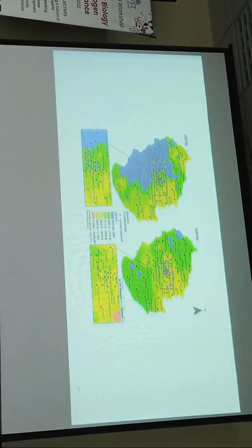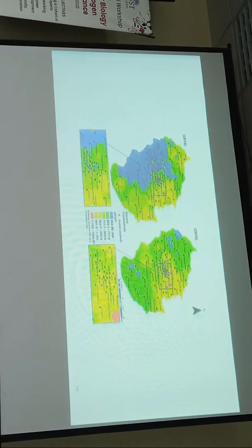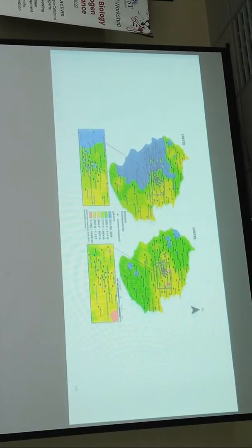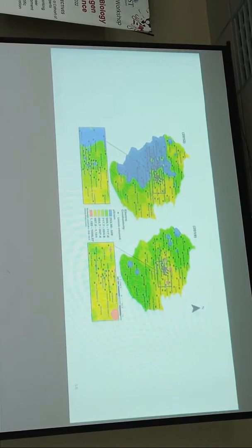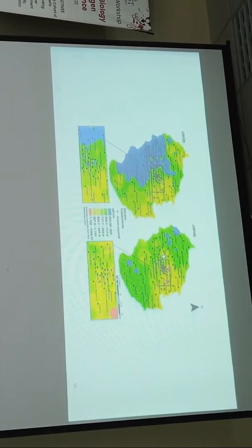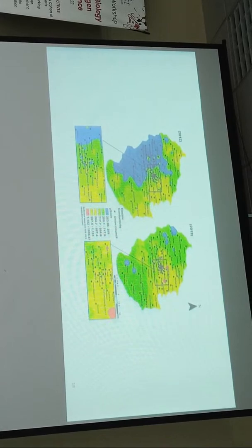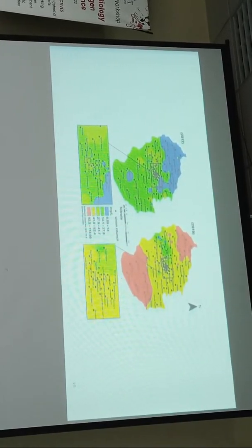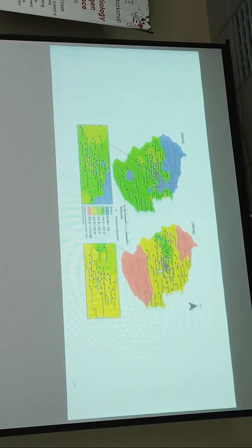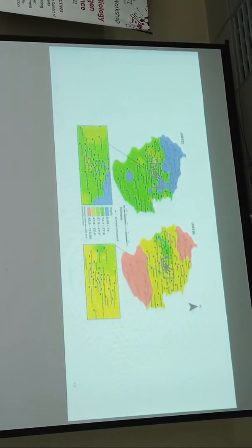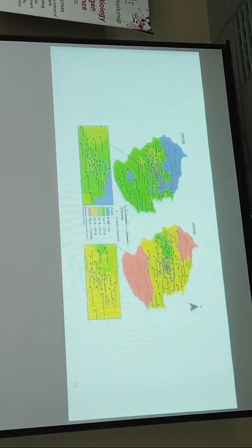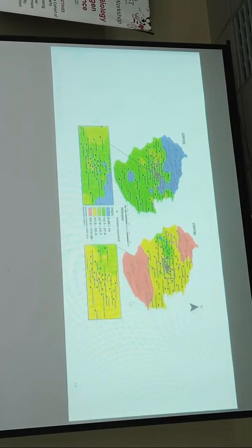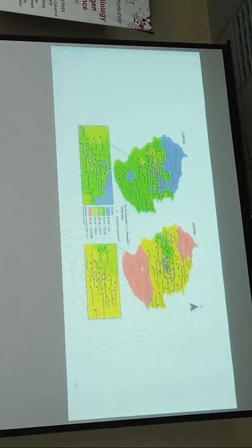The same thing with the electrical conductivity, there are no major issues, but in the central Peshawar area you can see some speckle points. And the same with the nitrate, if you look at the nitrate map, there is no issue in the 2012 data, but if you look at 2019, you can see a huge, high concentration of nitrate in the groundwater in the southern part.